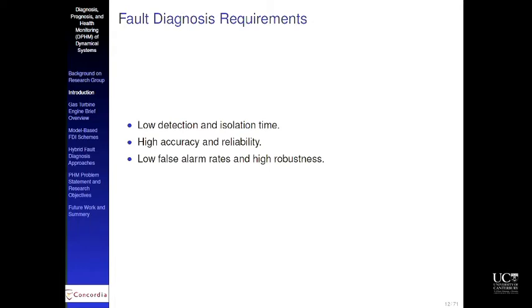There is nothing wrong with that actuator, but since my method was incorrectly classifying that actuator as having a fault, I start the recovery procedure when there was no need for that. Actually, that recovery can make it more unstable than the fault that was not even there. So it's extremely important that we end up with a low false alarm rate as much as possible.